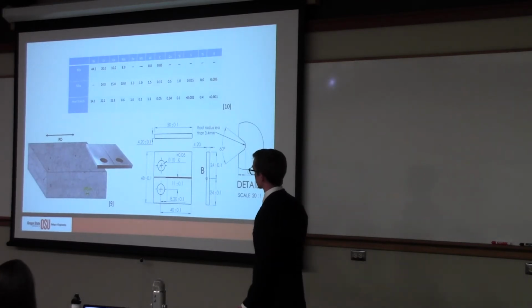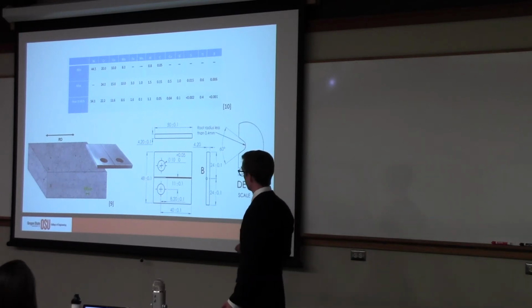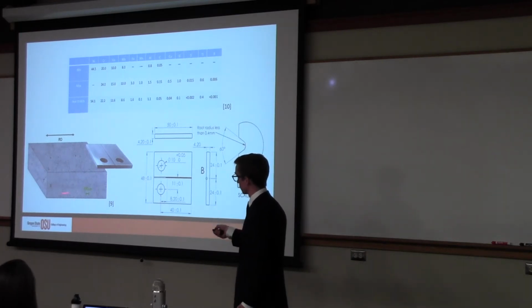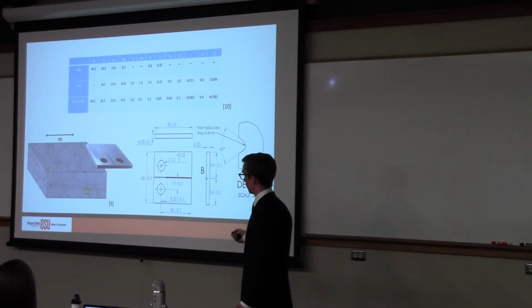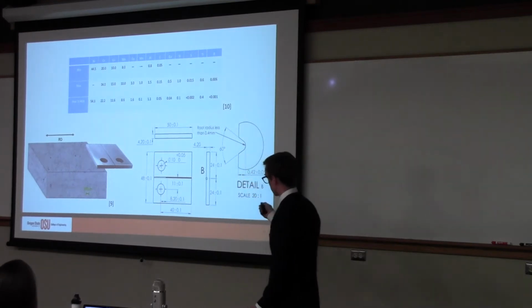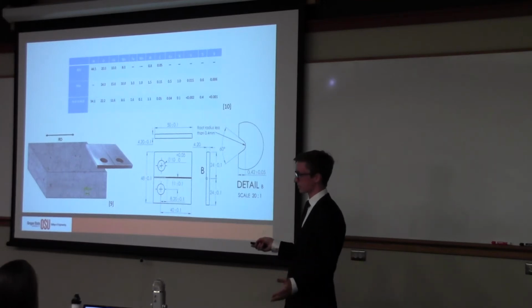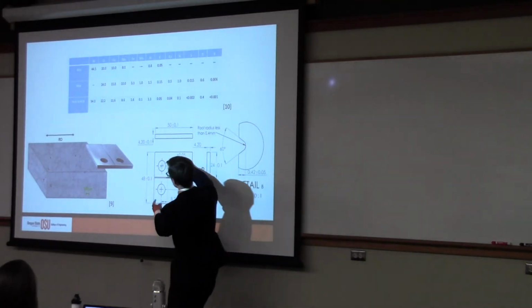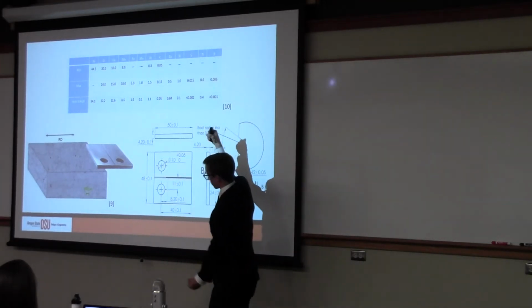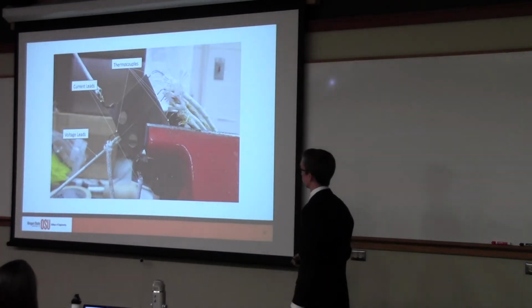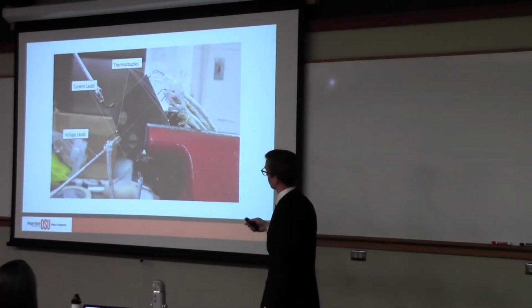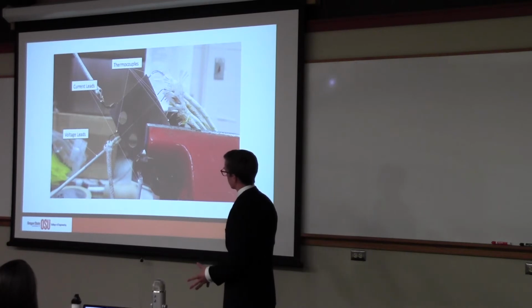That's the composition of alloy 617. It's got 13 alloying elements in it, plus I think there's some phosphorus in there. This is a microstructure done by some folks at INL. This is the orientation of our samples. This is a schematic of what our samples look like. Compact tension samples where you put pins in these holes and then you pull it apart with a clevis system, which I'll show you on the next slide. This is a sample when it's about ready to go into the machine.